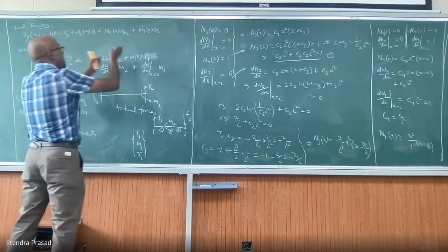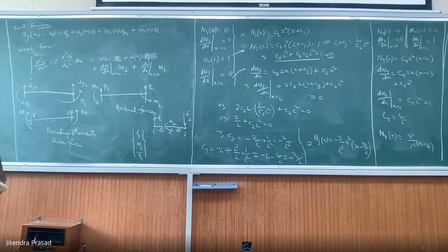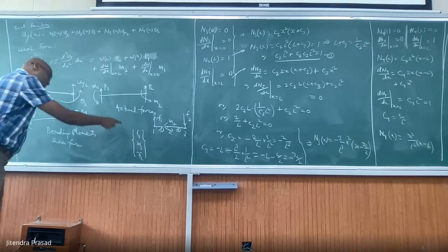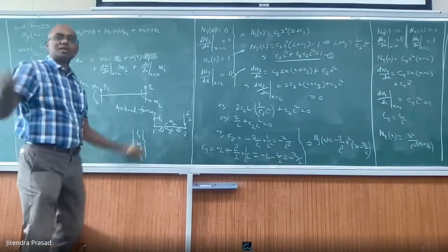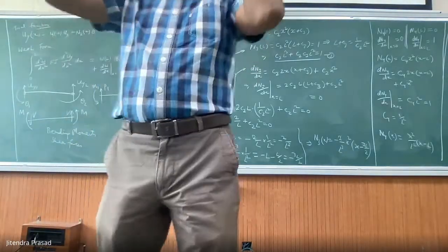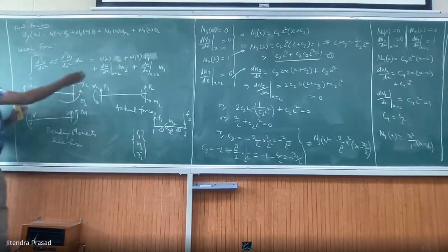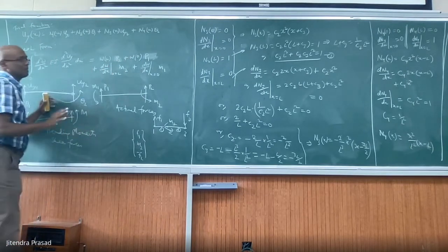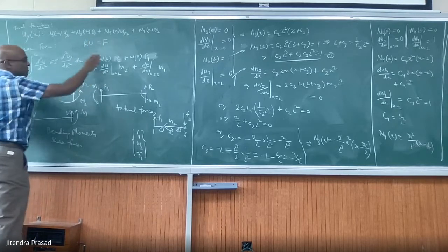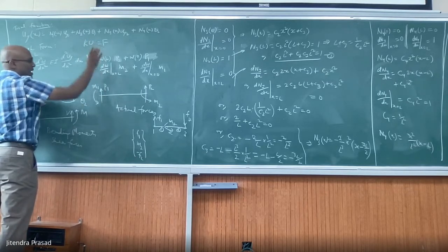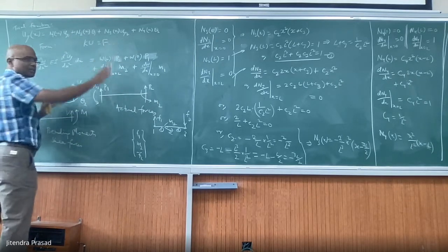Regardless of how you write here, finally it is the force that has to appear. Positive y direction, positive; anti-clockwise, positive. If otherwise, negative. Right there, that's it. You don't have to see how they multiply, how they translate into bending moment and all. This is just the mathematics. But the meaning is K times U equal to F, and F has its own sense. F has upward, positive; anti-clockwise, positive. That's it, nothing else.